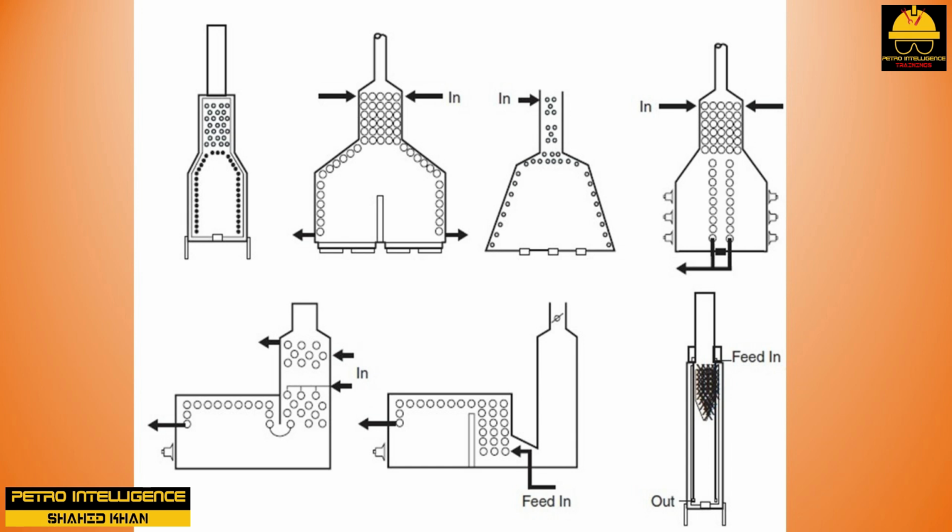Notice that the raw material feed to the furnace is preheated by introducing the feed into the furnace through tubes in the vented stack. The hot vent gases heat the feed before it reaches the tubes, which are in direct contact with the flames of the burning fuel gas. Reaction furnaces are used in the olefins and vinyl chloride unit.